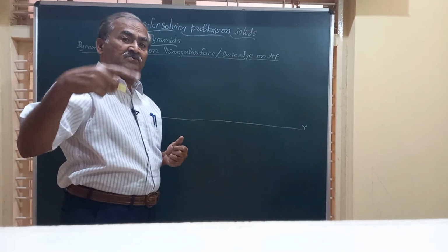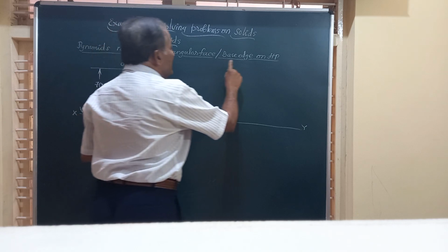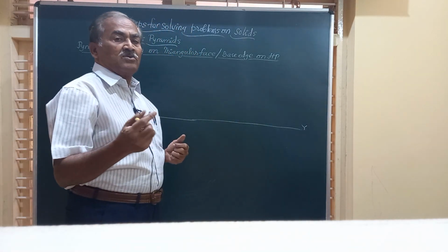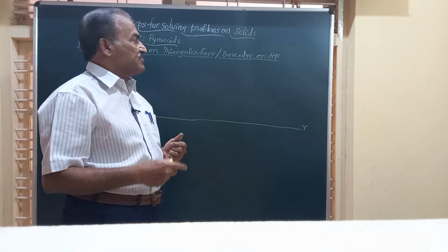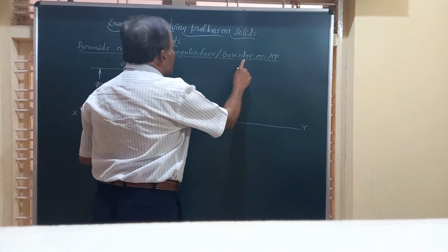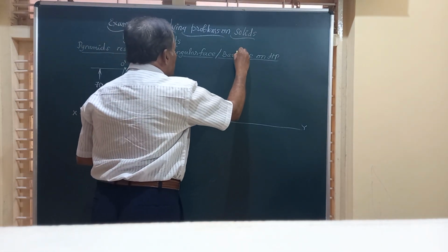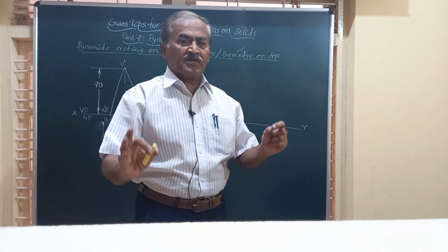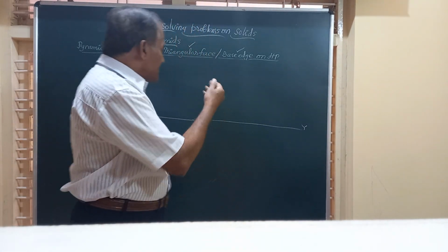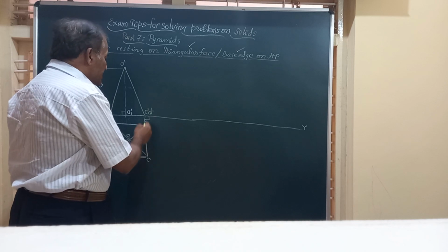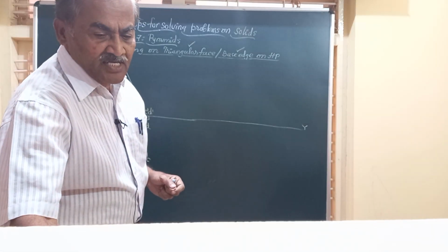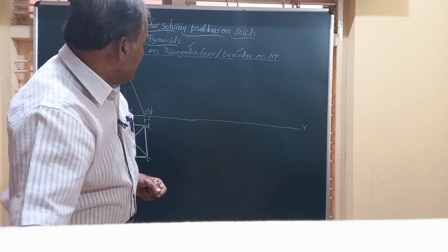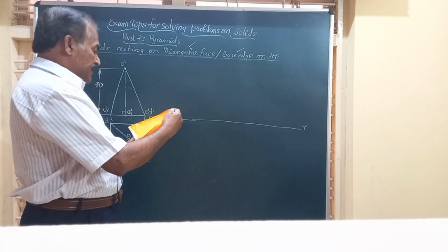like our rectangular face in prisms, base edge are one of the shorter edge in case of prisms. So when you find these terms, base edge or triangular face in case of any pyramids, then friends, place this on HP such that one of the base edges is normal to VP and it comes to your right side.